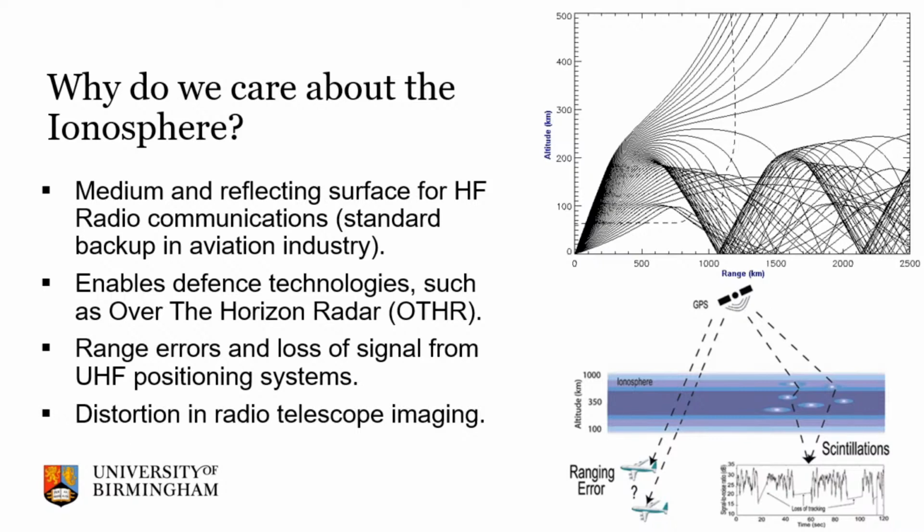Similarly, by what I mean in terms of a reflecting surface, if the frequency that you're transmitting is sufficiently below what I'll refer to as the plasma frequency of the ionosphere, which is just proportional to its electron density, I won't describe it any further than that, a signal propagated up towards the ionosphere will become reflected. This means that you can have extremely long-range communications by bouncing signals repeatedly off the ionosphere back towards Earth, towards whatever friend you have in Australia or Canada, maybe.